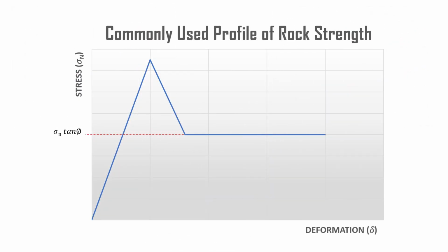Rock mechanics is based upon models of jointed rock or upon models of continua. Generally, the rock is assumed to behave in an isotropic, linear elastic manner until failure as determined by shear, when it suddenly changes its behavior to one controlled by friction on the sheared surface. This is quite unrealistic. Real rocks seldom behave in this manner. Sedimentary rock never does.